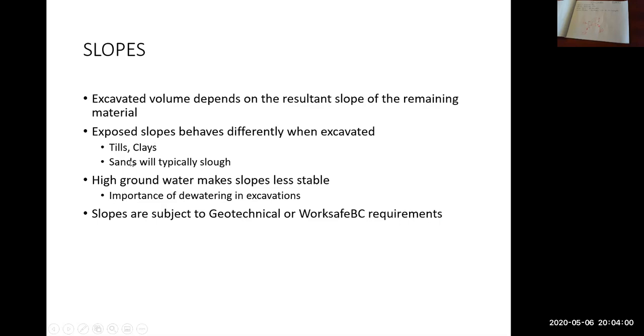Whereas sands, they will slough. The sand will flow to the bottom of the slope, basically. Especially when there's rain happening, an exposed slope will start to erode, and the material that's on the slope will end up in the bottom of the excavation.